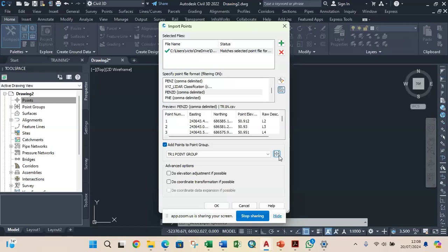It's like in AutoCAD. AutoCAD has a default layer, which is layer 0, which everything comes out with. If you're not giving a layer, you're working only on layer 0. If you switch that 0 layer off, everything goes off. But once you segment them into layers, you create a layer for your column, a layer for your wall, a layer for your beam, a layer for your slab, all these things. You can switch them on and off. That's the same principle Civil does here.